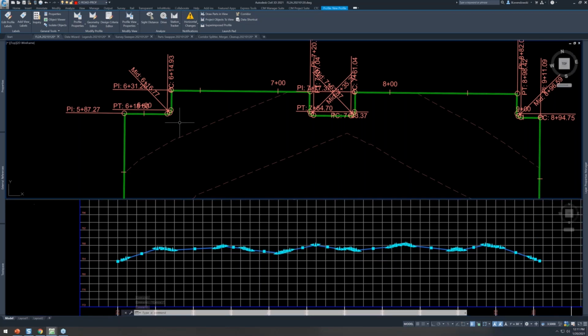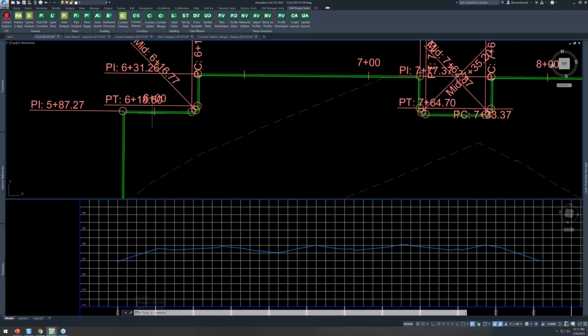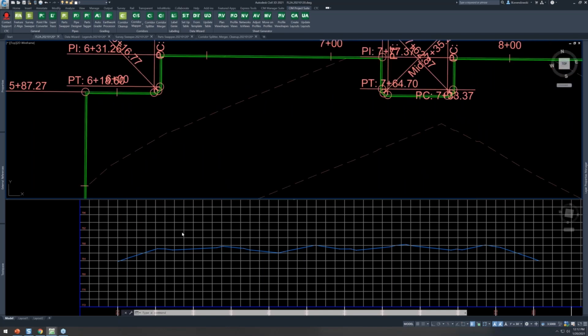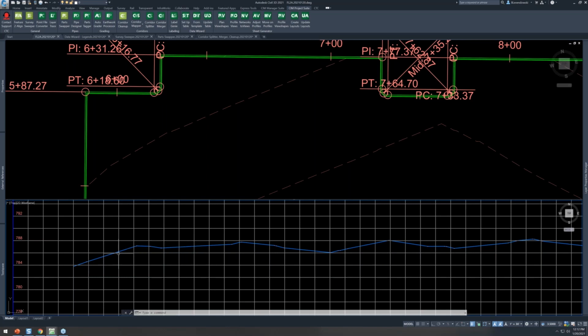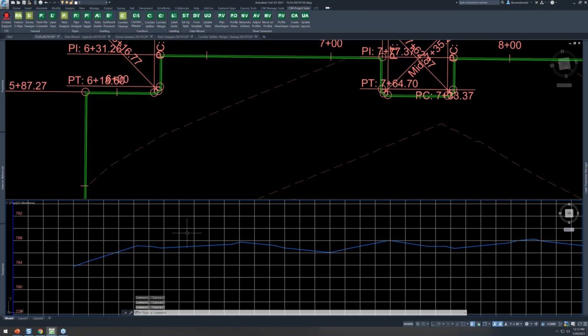Now, there's something to note here. I've had a lot of surveyor techs say, well, Brian, why don't I just explode that and make a polyline and create an alignment and then cut a surface profile from my finished grade surface. Part of the problem is you can't take a surface profile and export it in the same way you can on a layout profile. So in Civil3D, there are two distinct types of profiles, layout and surface profiles. What we want is a layout profile, basically the type you would create when you're creating a proposed profile. That's what we want. That's what we'll export to a Trimble RXL and other platforms. Now, there is kind of a convoluted approach.